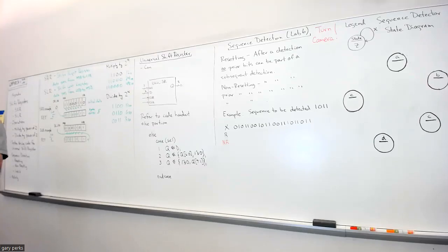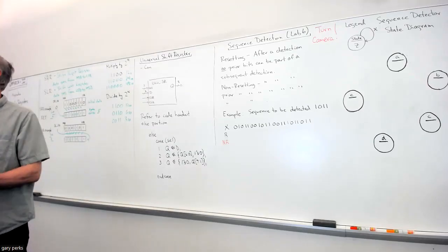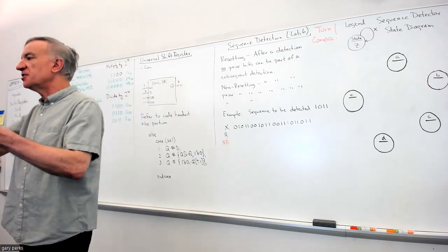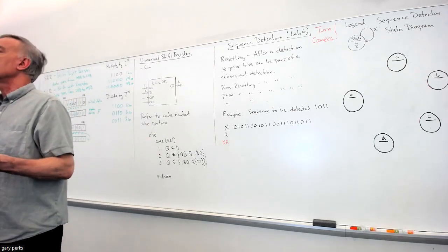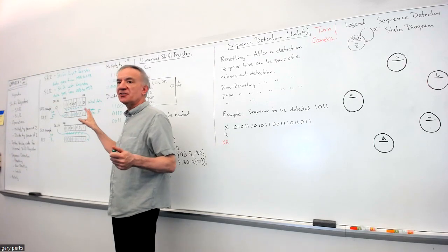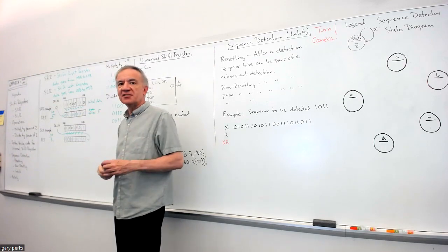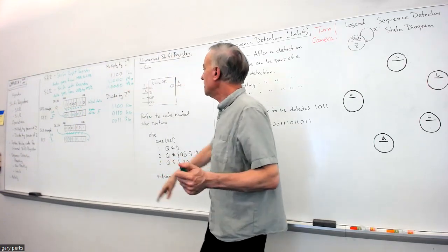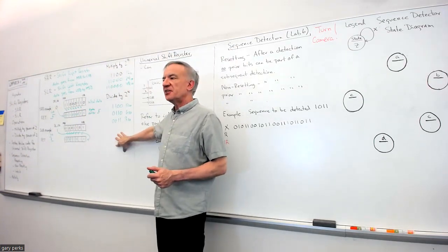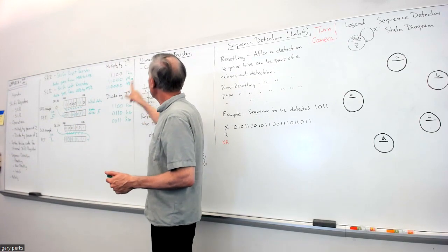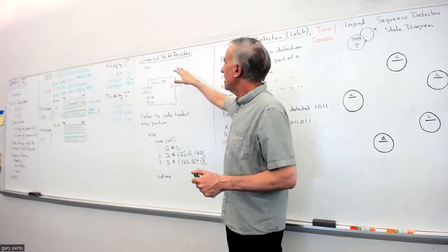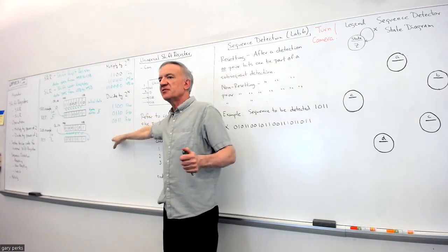And I think there's one exercise that you do in that class, one homework problem where you have to do a division by 4. Right? And this is the way you can do it, just by shifting right 2 places, bringing in zeros. All right, so any questions about shift registers? Because we got one more thing to go over with shift registers before we start a new topic. But any questions up to this point?